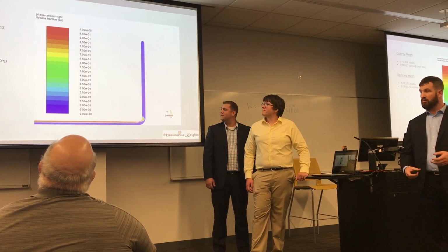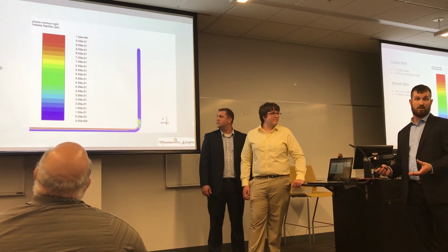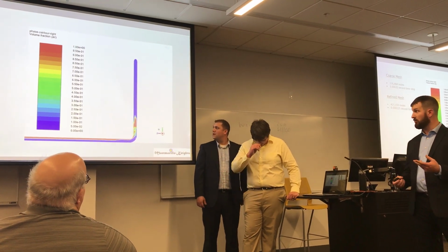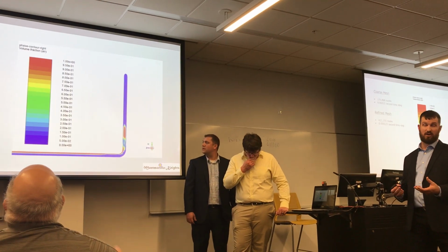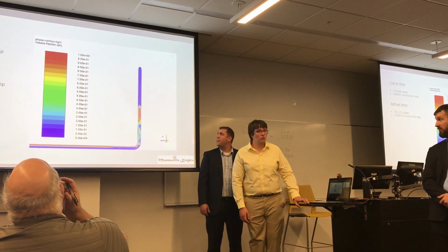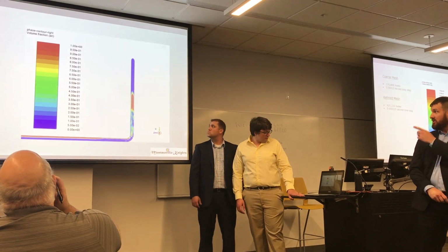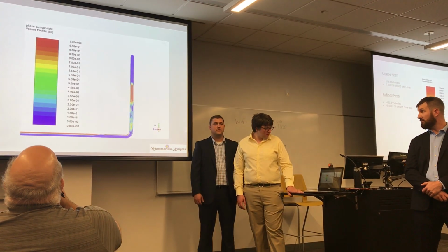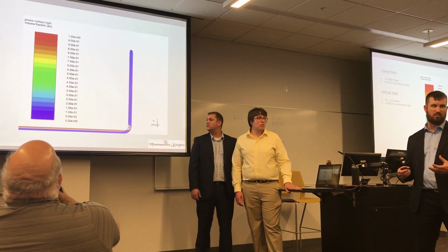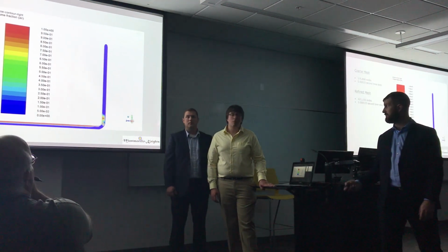Going into this, we wanted to run at least 2 simulations minimum for each model so that we could use a coarse and then a refined mesh in the hopes of comparing the 2 and getting grid independent results. Right here you can see a phase contour animation for the bench scale model. And you can see we get pretty good slugging effect in the pipe. For this model we used a laminar model and it was only stable for about 10 seconds of flow time.